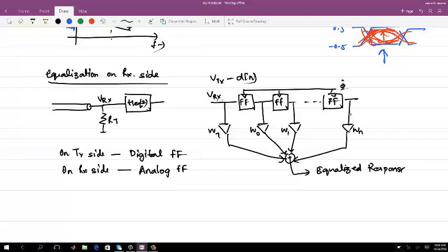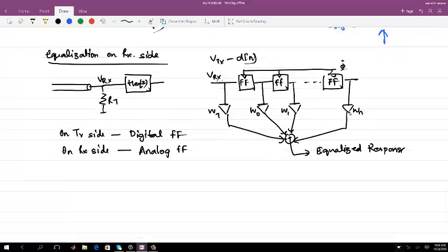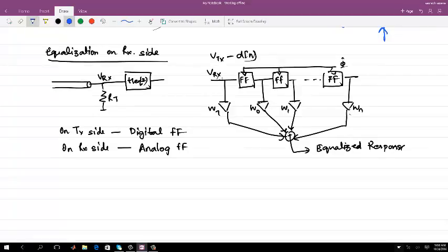That's the flip-flop. At the edge it samples and the rest of the time the bit remains the same. Now, the simplest flip-flop which you have come to is a simple switch, track and hold. You sample at the clock, hold the voltage, and pass it to the next.